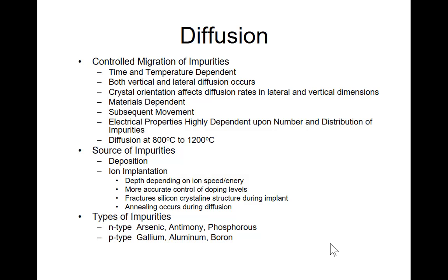And so the temperature, as we said, is typically 800 Celsius to 1200 Celsius, but sometimes you want it to go faster, go deeper, then you can even go higher, up to 1400 C. People also do so-called low temperature diffusion for some of these newer 3D processes. If you don't want to damage something that you already made, you can do so-called lower temperature diffusion, maybe at 400 C. But most of them are in the 800 to 1200 degrees C.